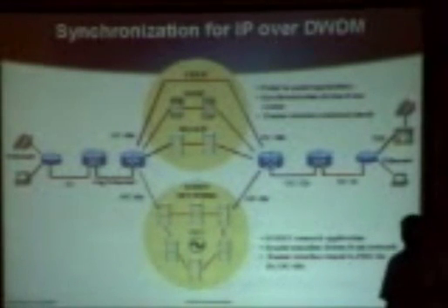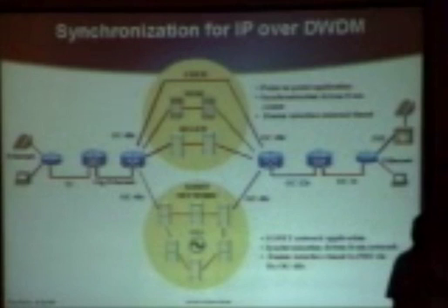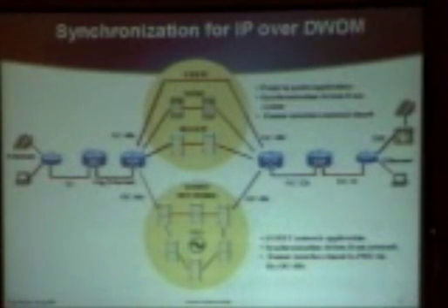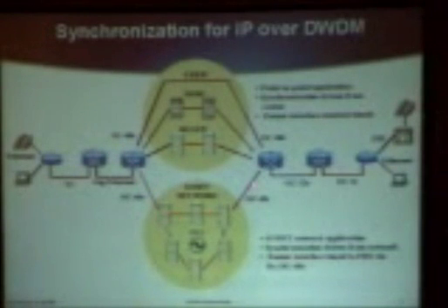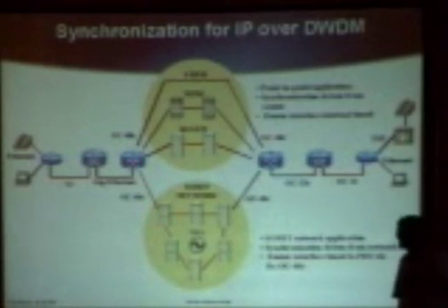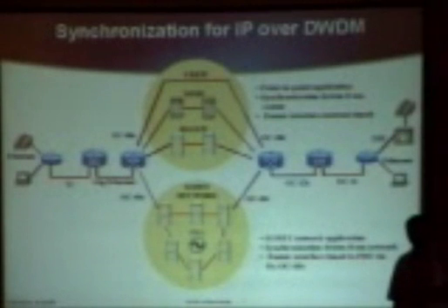What we do in our products is we relax the clock accuracy to 20 parts per million, which happens to be the very edge of the SONET spec, so that we can bring a low-cost clocking solution that's still SONET compliant and works great over WDM. If you're using the router to connect your POS links into a SONET network, all we do is loop time off the stratum clocks that are inside the SONET network to provide us with local clocking. So in the router you have the precision to connect synchronously into a SONET network, but you also have a simpler solution if you want to go straight over WDM, because it's just point-to-point.